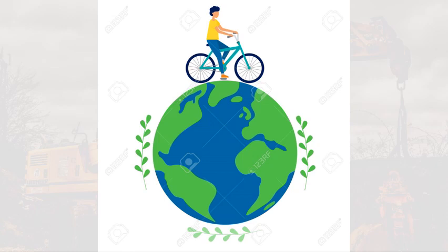In fact, some early automobiles had rolling cylinder drives inside the transmission, as do some present-day snow blowers and garden tractors that use a rubber-coated wheel rolling against a steel disc to transmit power from the engine to the wheels.